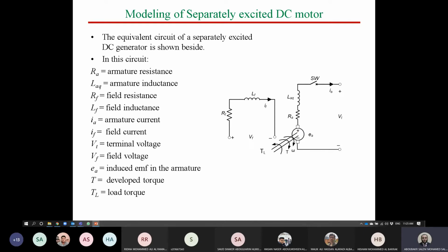So, in order to start with DC motor, Shabab, we start from scratch with the mathematical model of the motor. We have field circuit, which includes R and L. Also, we have armature circuit, which includes R and L. We have supply voltage. We have EMF. We have mechanical parts, which include the shaft, and this shaft will move at a certain speed by electrical torque T, and there will be a load connected with a load torque TL. One can say we have here a DC motor.